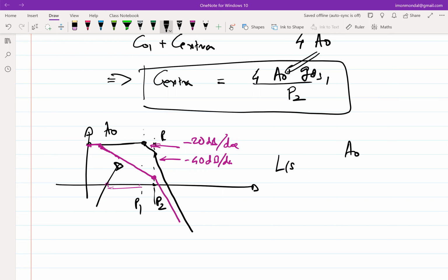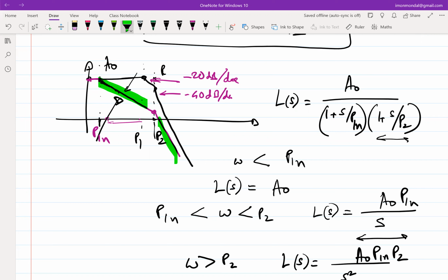Intuitively this should make sense, because when does your feedback exist? Your feedback exists as long as your gain is high. And if the gain is high, you want it to behave like an integrator. Your gain is high below omega u loop, so you want it to behave like an integrator below omega u loop.